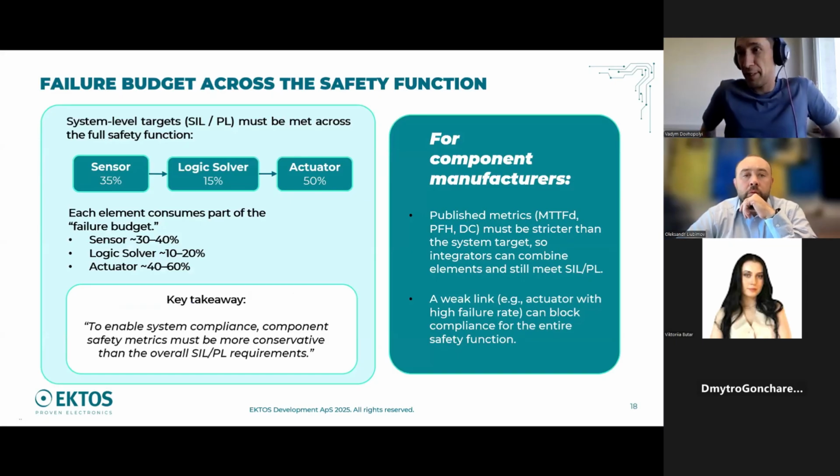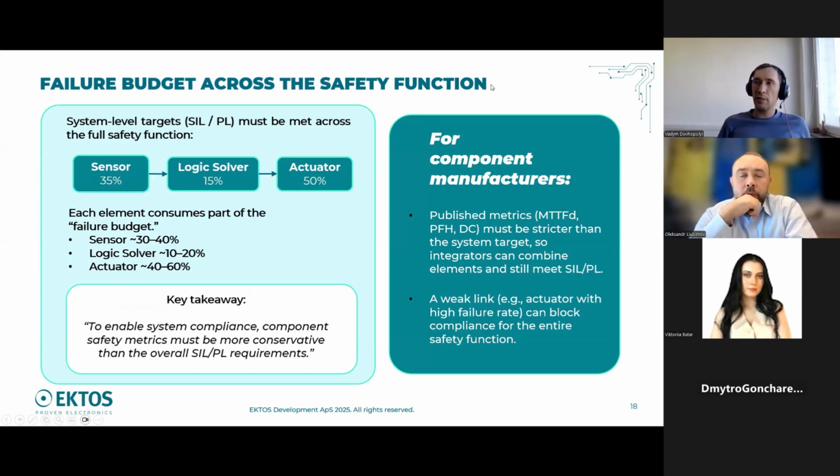Yeah, and here is a very important thing to understand. Specifically if you are a component developer, like of a sensor or valve, standards require some values of this metric, but you have to remember all the time that it is not for the valve or the sensor or the solver. It is a metric for the entire functional safety function. It includes sensor, logic solver, and actuator.